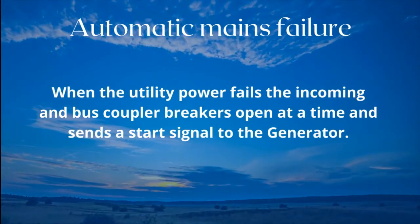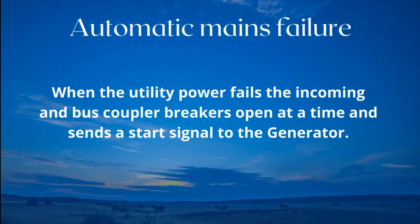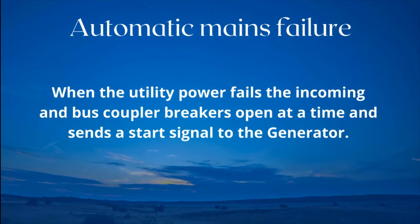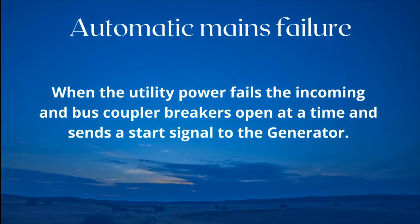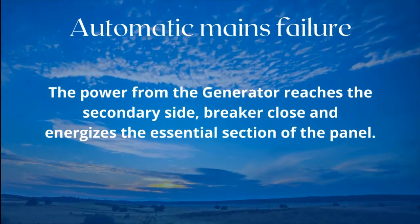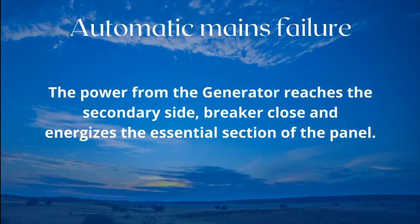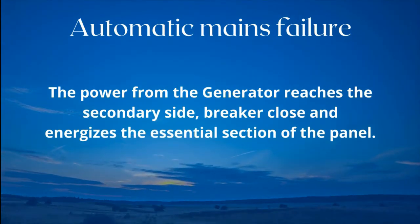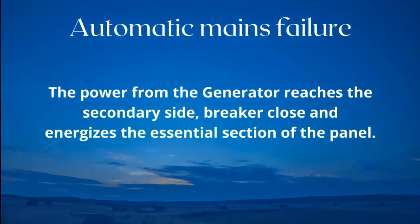When the utility power fails, the incoming and bus coupler breakers open at a time and send a start signal to the generator. Power from the generator reaches the secondary side, the breaker closes and energizes the essential section of the panel.